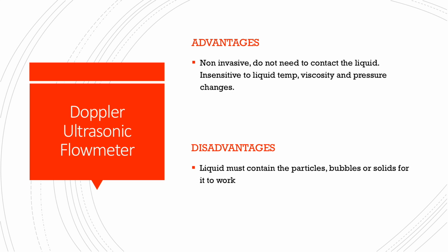Reasons to use a Doppler ultrasonic flow meter are that it is non-invasive and you do not need to contact the liquid. This is also insensitive to liquid temperature, viscosity, and pressure changes. Disadvantages are that the liquid must contain particles, bubbles, or solids for it to work.